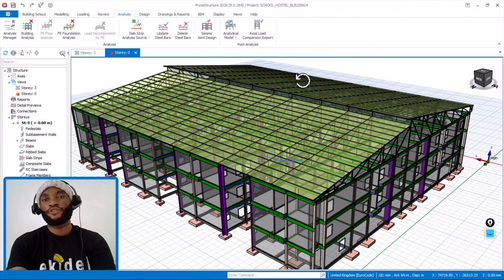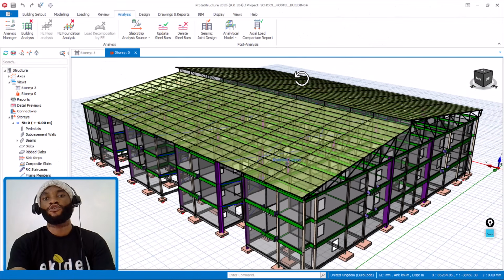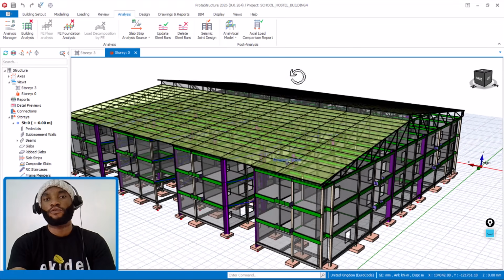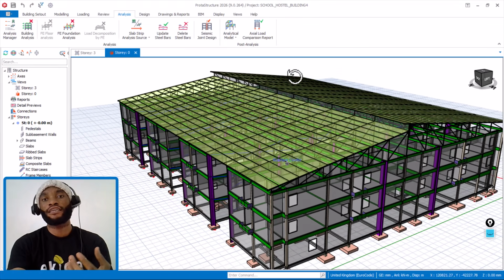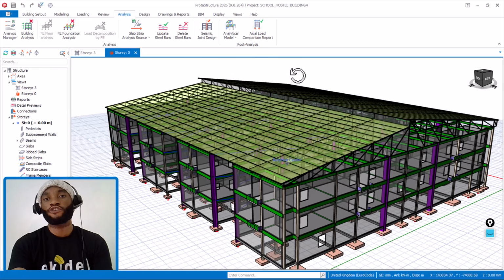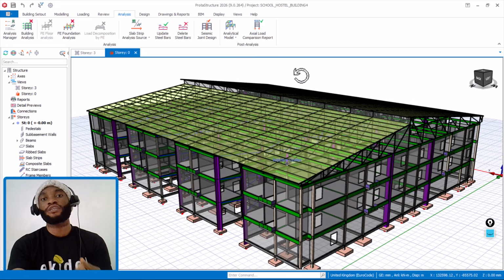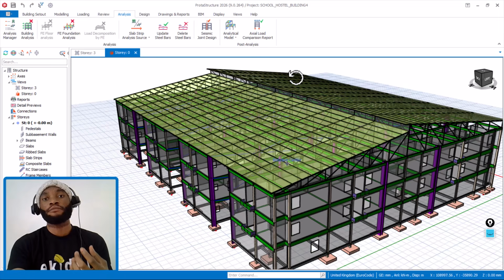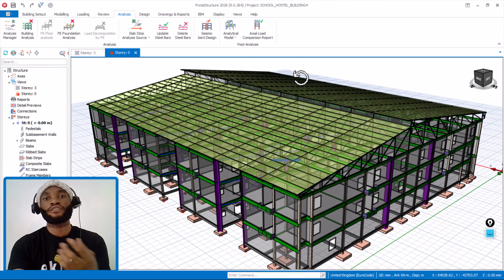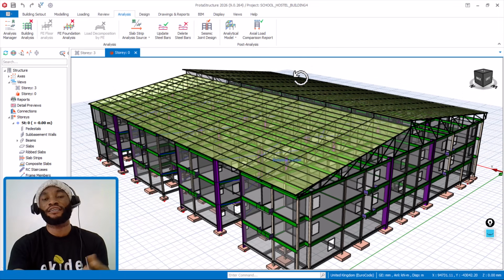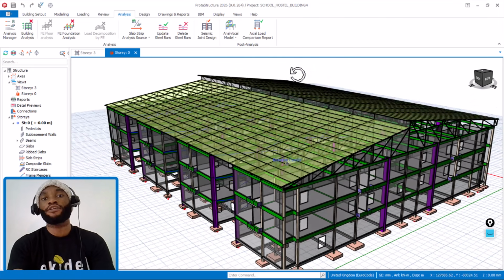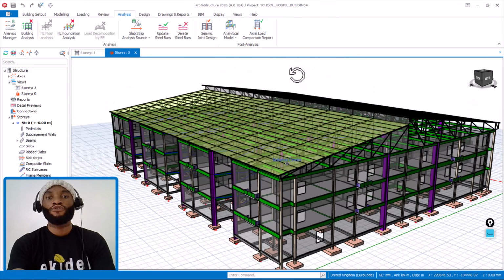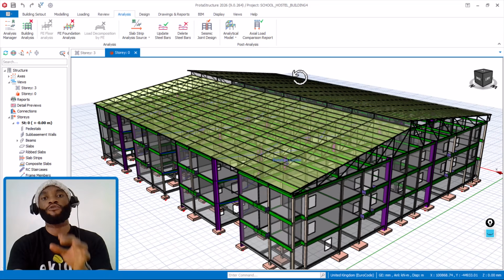Hello, most of you are actually performing overdesign on your columns when you're using this software, without even knowing. You are designing with more reinforcement for your structure than what is actually required. And most times when you compare it to other software, this one is giving overdesign, but that's because you are not inputting the right factor which you're meant to use when you're designing your columns.